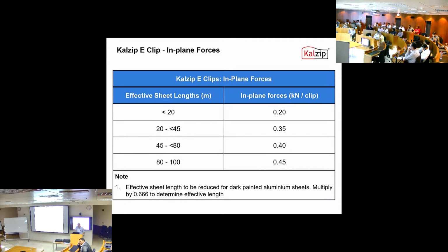First of all, the deck sheet is part of the structure, which is normally, let's say, an air conditioned warehouse, so constantly at 25 degrees, let's say. And the top sheet, according to the weather, ranges between summer and winter around maybe 50 degrees or 40 degrees regardless. So the top sheet is always in movement, and the bottom deck is always at the same temperature. So you have the movement on the top. So, okay, I have one skylight. I can move the fixed point and put it near the skylight on both sides, and the system breathes for the other two areas.